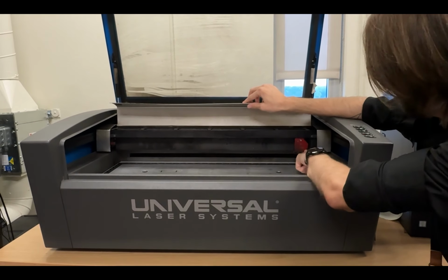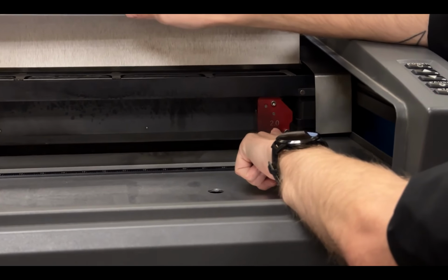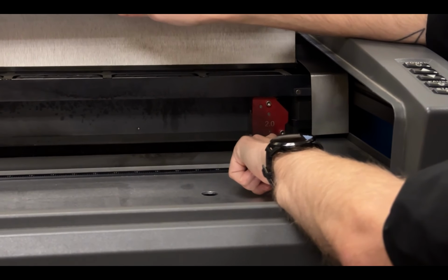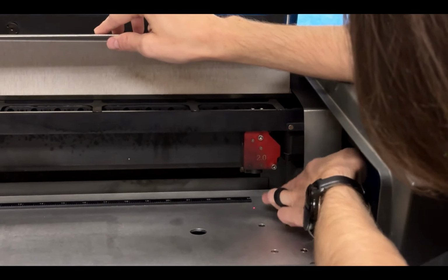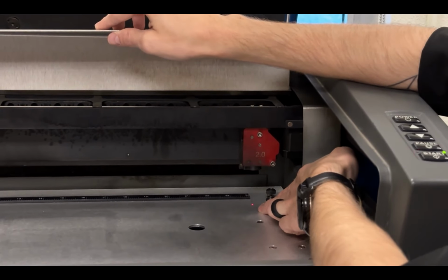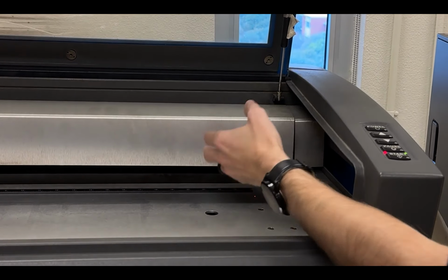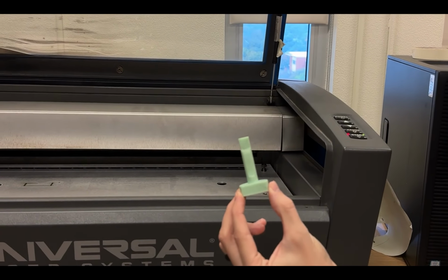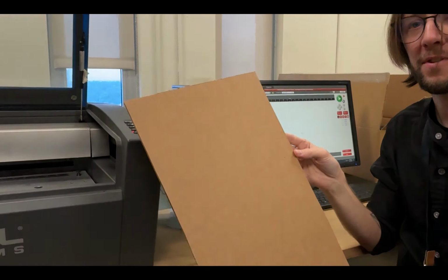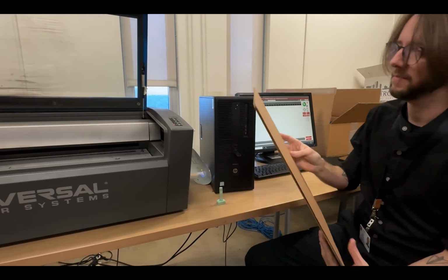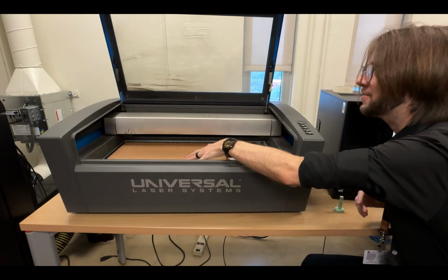The same thing can be said for here, where you see a 2.0. That 2.0 stands for 2 inches from the bed, which is the perfect autofocus. That's what it stands for. So the tip of this edge of the red right there needs to be exactly 2 inches from the top of the material, not the bottom. And of course, I've made a little apparatus to show you what we're going to have to do. So once we have the file there, and once we have our wonderful piece of material, which today hopefully will fit, I think. This should be okay. It's not going to get all of it, but that's fine for today.